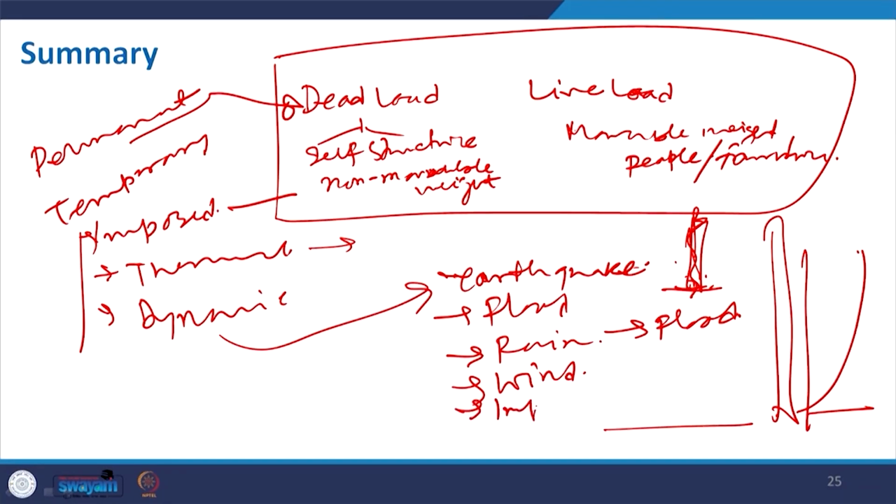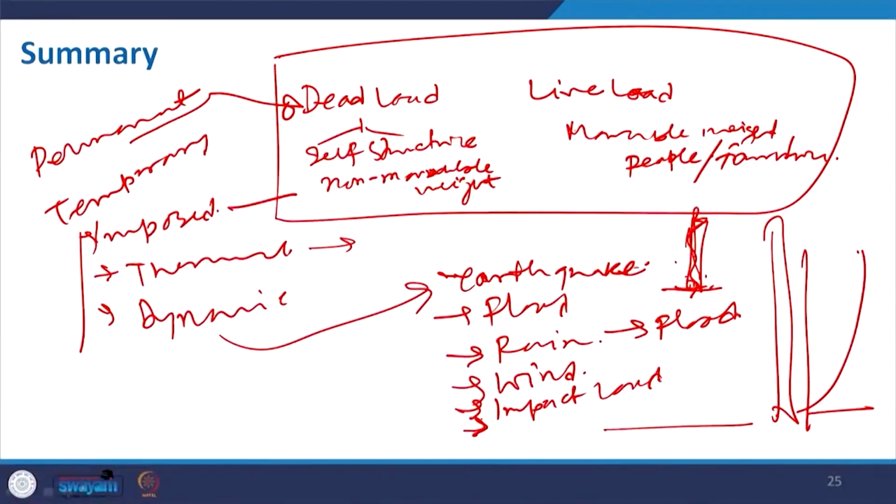And apart from that, we also discussed the impact load. All of a sudden you just throw a heavy bag on the floor, or some equipment. That will create some impact on the floor or the wall. And then we also discussed the resonant load, which is also very vital when we have such gatherings. With music, when multiple waves synchronize with each other and propagate, they create a huge load on the structure.